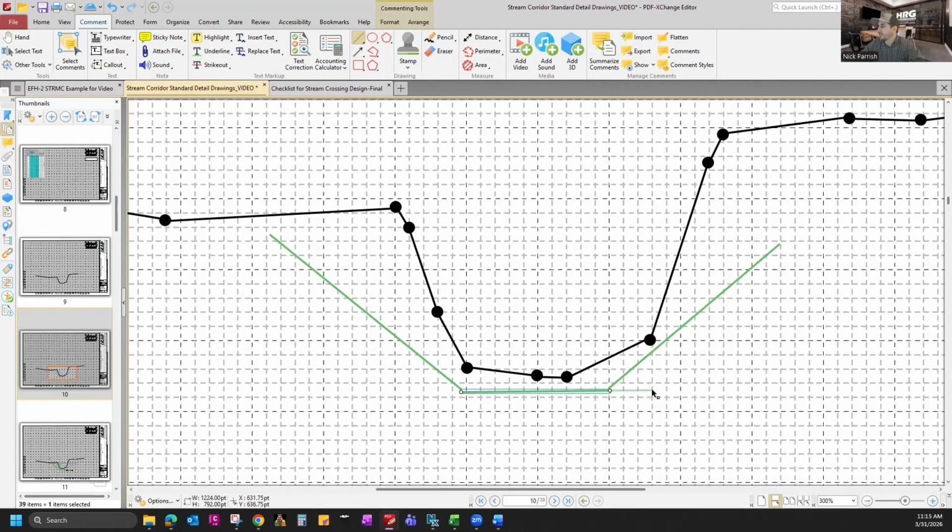And then we'll see how far out we need to go to get an even number here, divisible by 4, seeing as the precast concrete slats come in either 4x10 or 4x12.